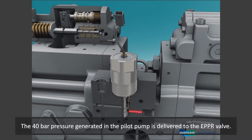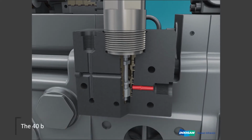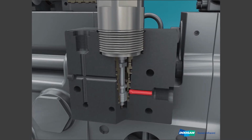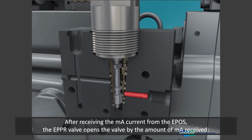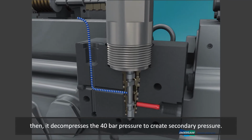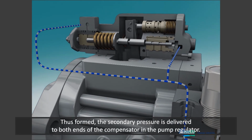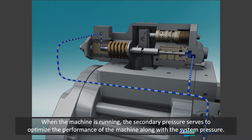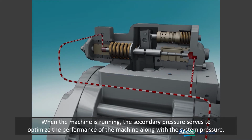The 40 bar pressure generated in the pilot pump is delivered to the EPPR valve. After receiving the milliamp current from the EPOS, the EPPR valve opens the valve by the amount of milliamp received. Then, it decompresses the 40 bar pressure to create secondary pressure. Thus formed, the secondary pressure is delivered to both ends of the compensator in the pump regulator. When the machine is running, the secondary pressure serves to optimize the performance of the machine along with the system pressure.